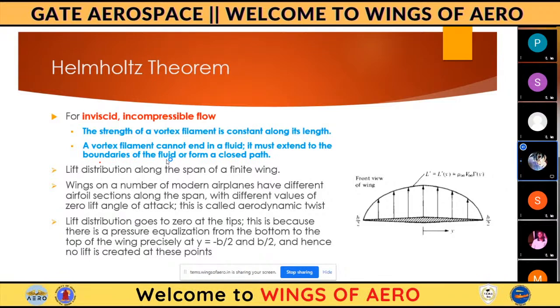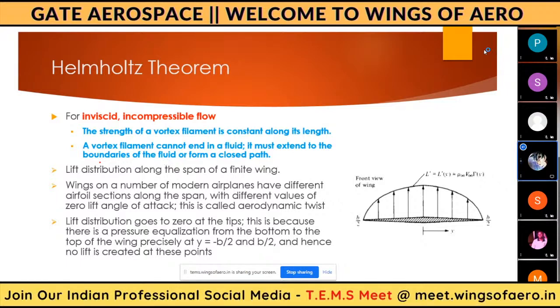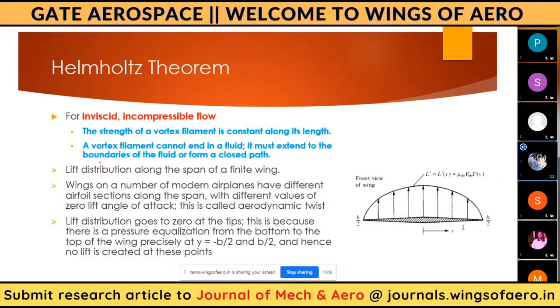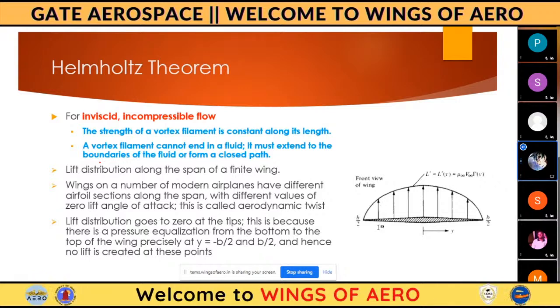Okay, fine. Then are we calculating any disturbance or any type of pressure force movements after the test section? We are not calculating that, right? We will see only the pressure difference: stagnation pressures and static pressure points will be kept before the nozzle section, and in the diffuser section also. Other than that, we won't calculate anything beyond the test section.